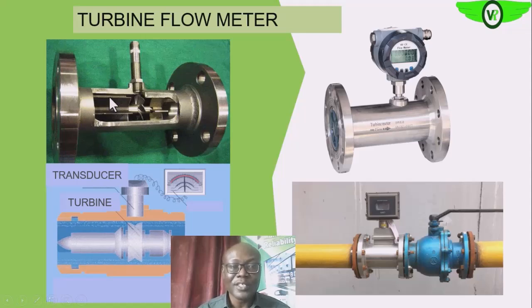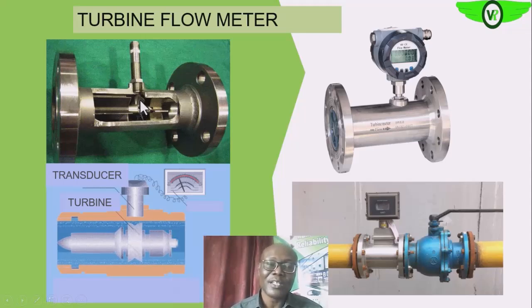So this is the flow conditioner, to help us have as much laminar flow as possible, directing the fluid onto the blades. Are we getting it? Between these two blades, a specific volume would have passed this section of the flow meter. So this is a pulse counter, a pickup anyway. It counts the number of times each of these blades pass through it.